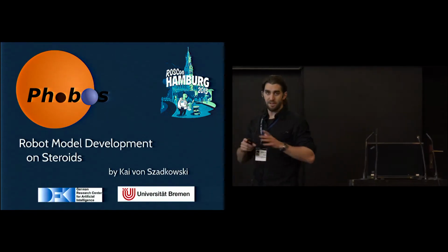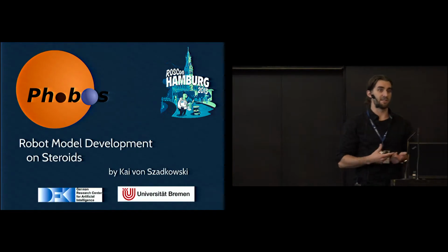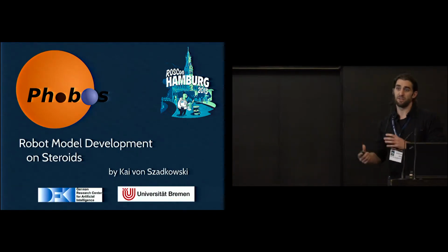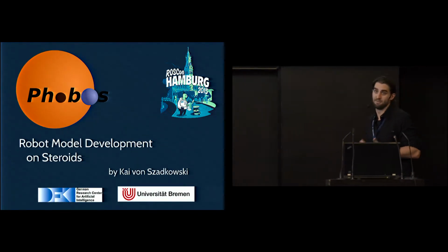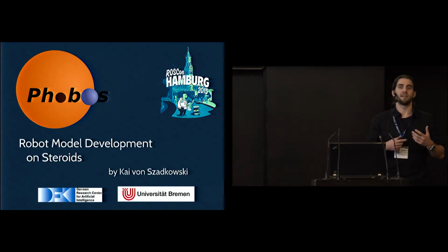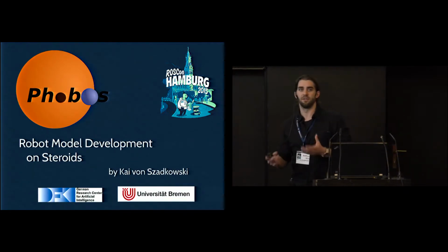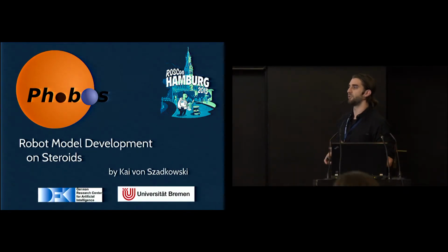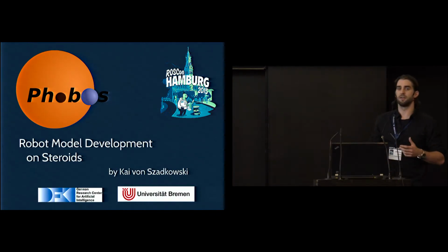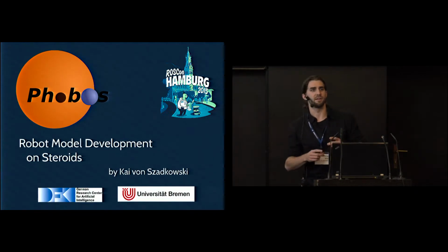So there are already ways to kind of mitigate this problem. There's, for example, Xacro, which lets you reuse parts of your URDF that you've already coded, but it still requires you to code something yourself. And then you have stuff like plugins for SolidWorks that export the general kinematics to URDF. But most of these, and I think that includes what the ROS Industrial guys were talking about, this CAD2ROS,